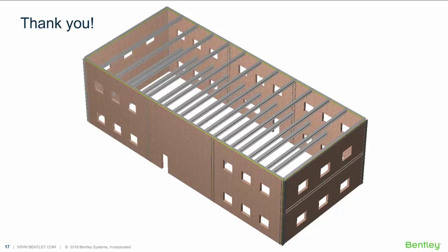There's no partial connection between adjacent walls, and that's true of both types of loading, gravity and lateral. So it's just a matter of engineering judgment if you actually want to place that physical gap there. As of now, the options are to either physically model a small gap or connect them and get full continuity across the joint.